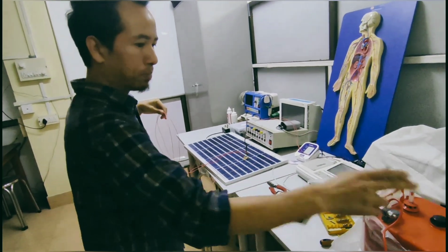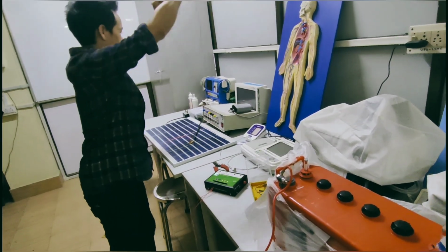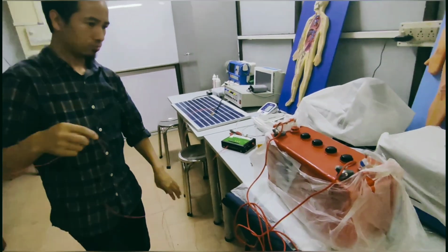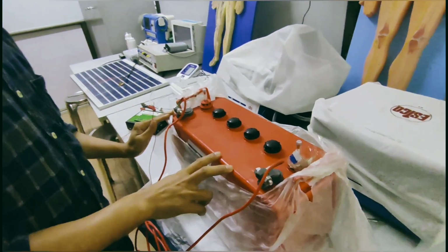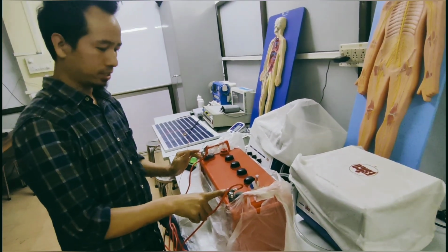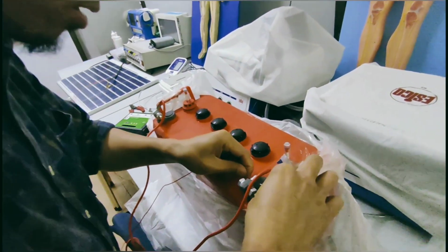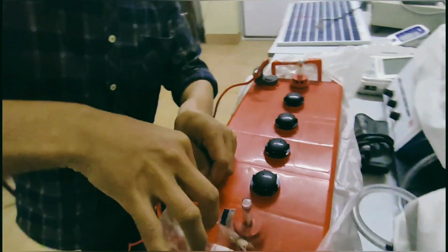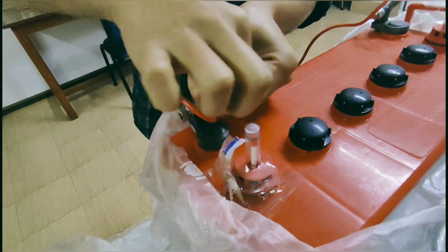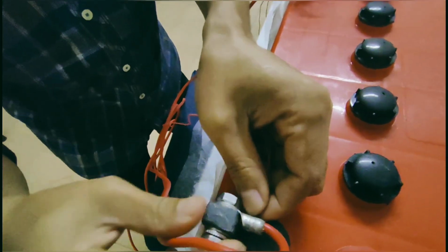Now let's connect the battery to the charge controller. You have to make sure that you don't short circuit the positive and the negative of the battery. So this is the positive terminal and this is the negative terminal. So just to show you, I connect directly like this. In fact, we have to insert the wire into a lug, trim it and then fix it on the battery terminal using a nut.